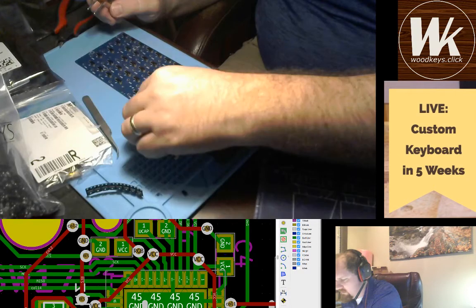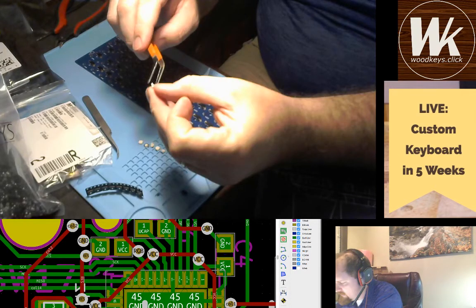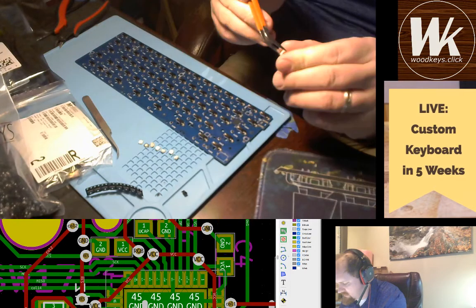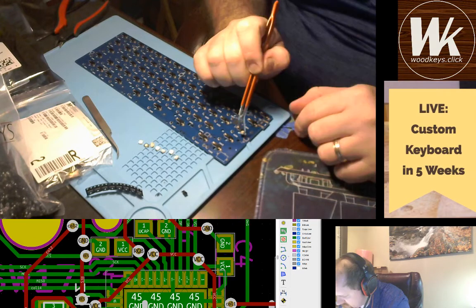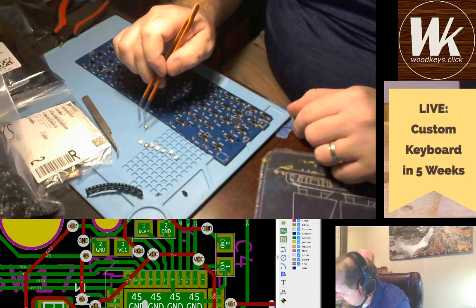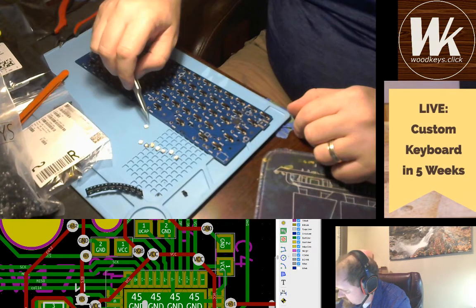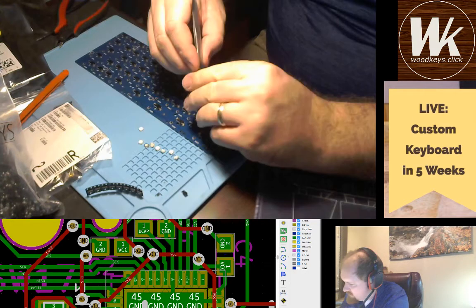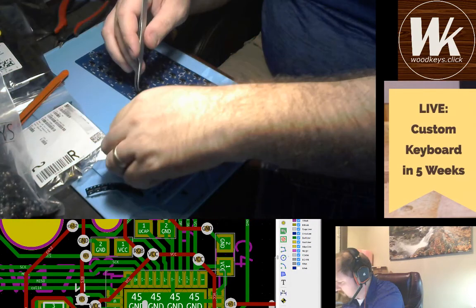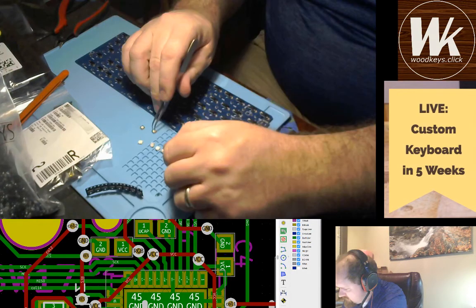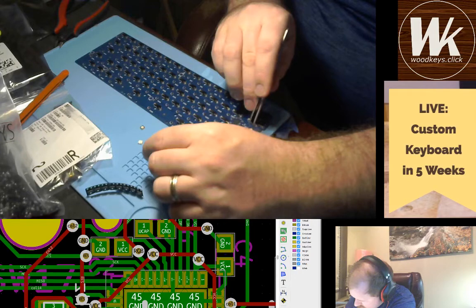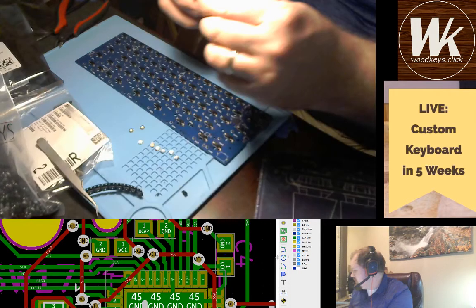So they have a little notch on one of the corners, and that indicates which corner is which. So you do only have a specific orientation, and I've got a corresponding notch on my silk screen on the PCB. The thing is sticking so bad. Let me see if I can use these tweezers. These are just a little small. It's not going to work. Just going to get the sticky off.